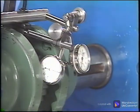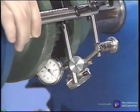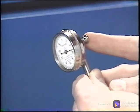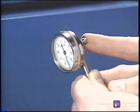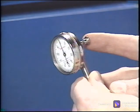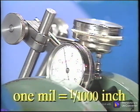As the shaft is turned, the tip riding on it changes the dial reading with any change in the relative position of the shaft. When the plunger is pushed further in, the needle moves in the positive direction. When the plunger moves farther out from the dial, the needle moves in a negative direction. Most dial indicators are designed to measure in mils. 1 mil equals 1/1000th of an inch.